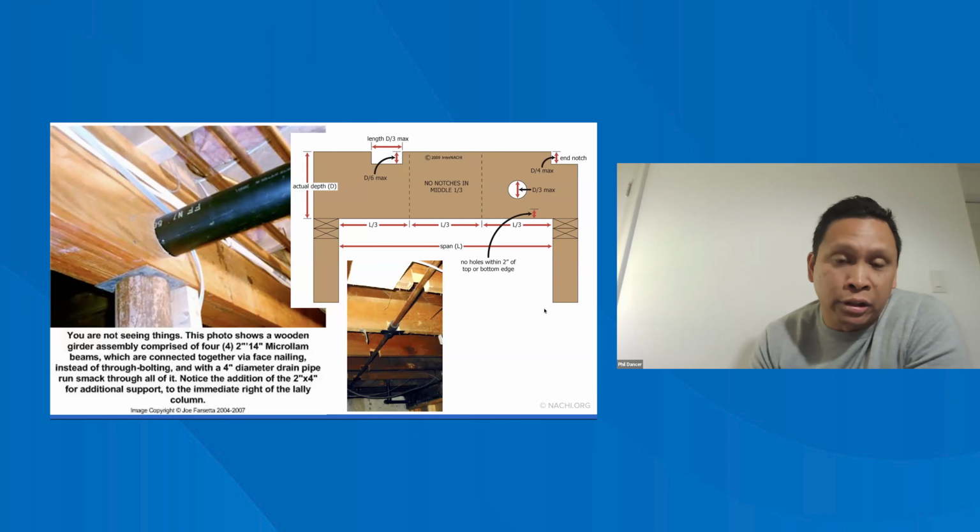I will say, I was actually doing a pre-drywall inspection the other day where the builder runs I joists, and they've had a decent amount of warranty claims, so they're not going to allow their contractors to drill holes, even in the pre-approved spots anymore.